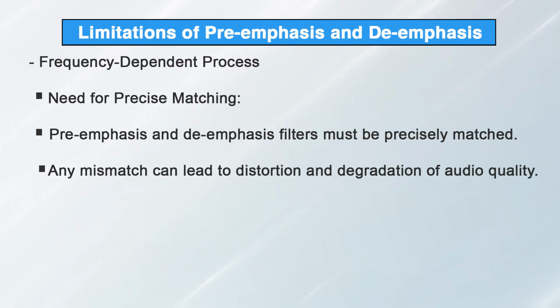Moreover, the process is frequency dependent, which means that the pre-emphasis and the de-emphasis filters must be precisely matched to ensure proper signal restoration. Any mismatch in these filters can lead to distortion and degradation of audio quality.